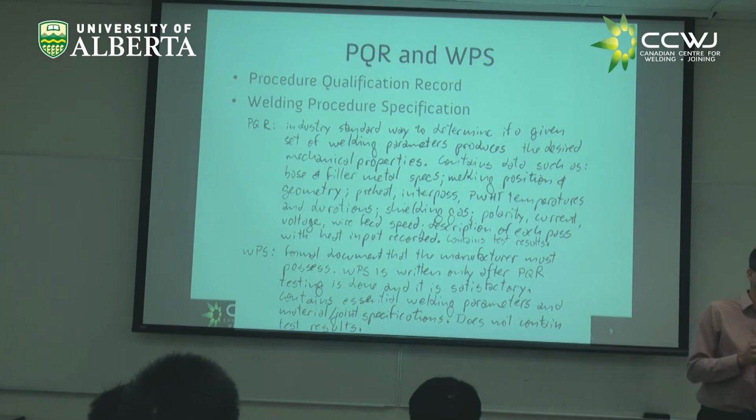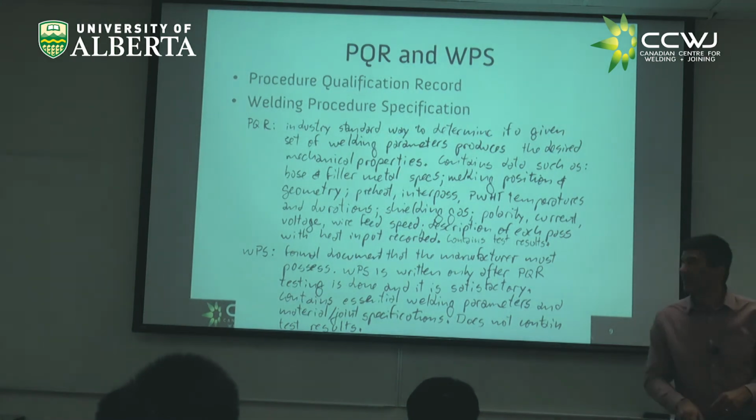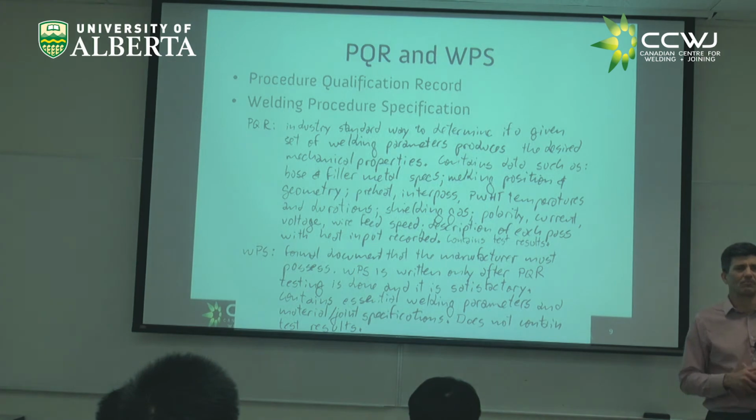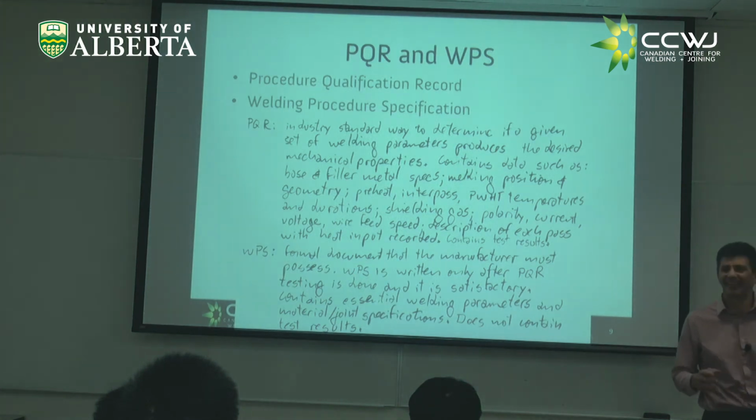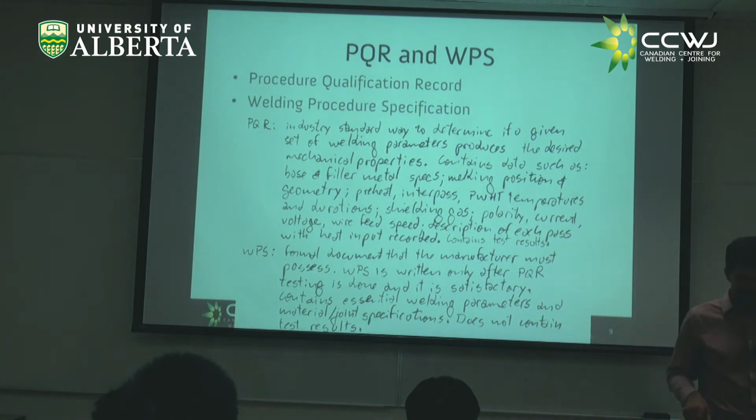So among the welding people, and those are the real practitioners, not like me, they think a good joke is to say, oh, they did the PQR after the WPS, haha, right? But it's a somewhat sad joke. Very often, you tell the welder what to do, and then you realize, oh, I didn't check if what I told the welder to do is going to accomplish what I needed.